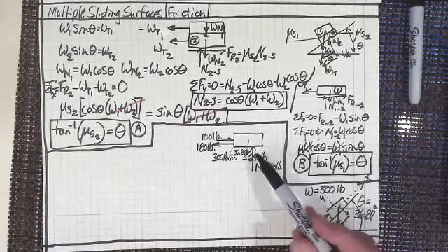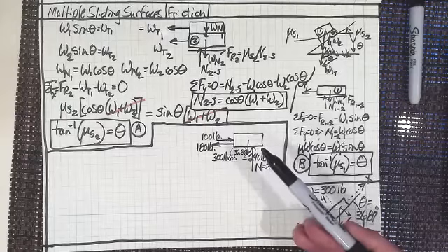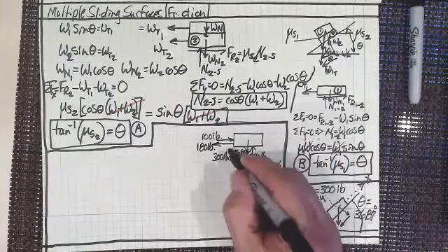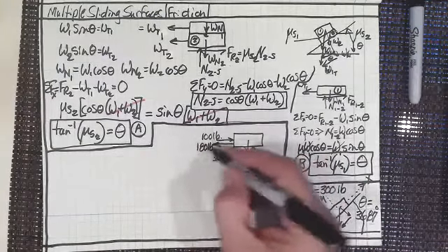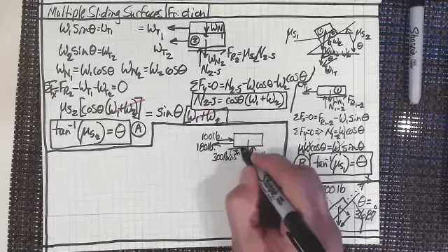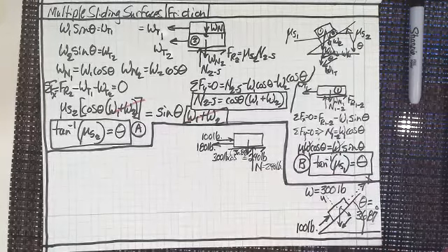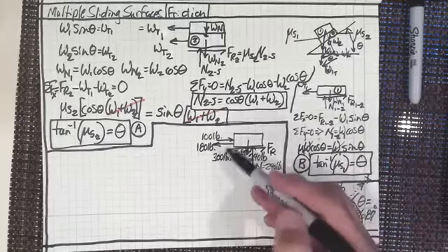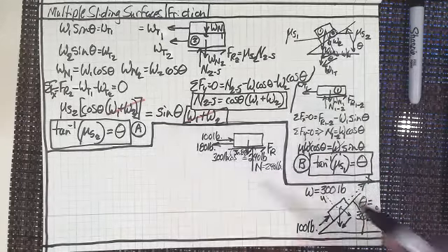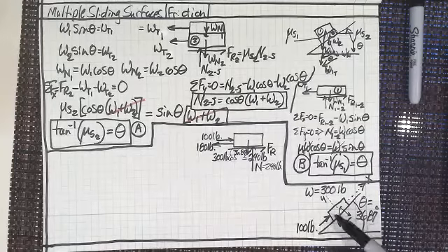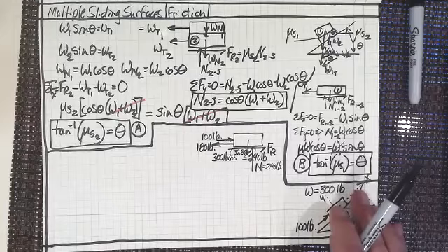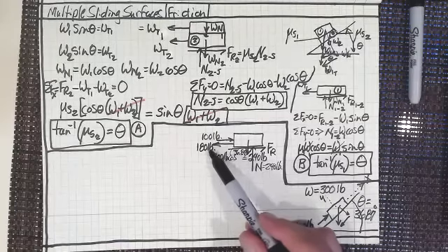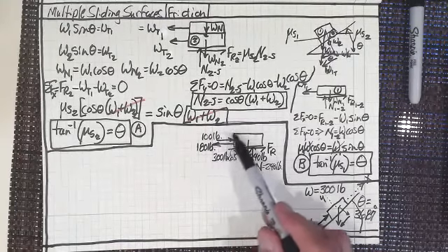So when we look at this, we have to take into account now, because the impending motion is to go to the left. I think everybody can see that. So we can see that the frictional force is going to work to the right, right? And that frictional force is going to grow. Now, is there impending motion? Is there going to be motion of this down the inclined plane? Well, that all depends on if F sub r is greater than 80 pounds, isn't it? Can everybody see what I've got here? That the difference here is 80 pounds.